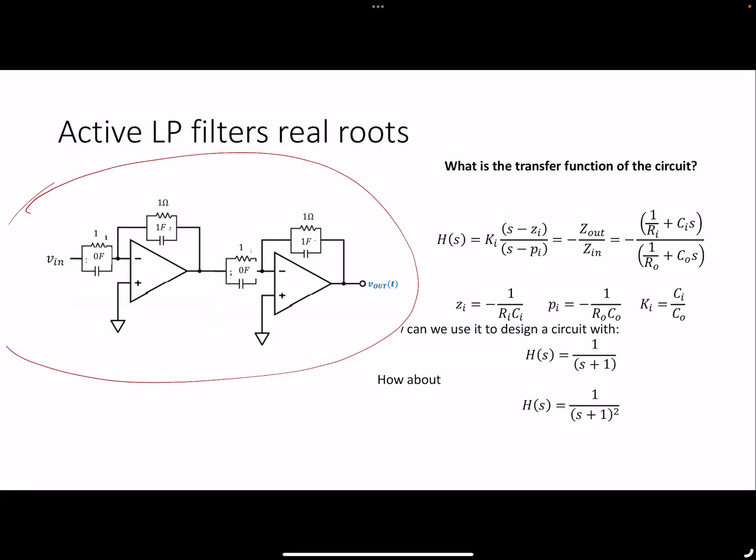In an exam, you're either going to be given a multi-stage circuit and you're going to have to figure out the poles or zeros, or you should be able to, if I give you an expression like K (s+3)(s+5)(s+7), design a filter that satisfies that. If you can do that, that's it. That's all you need to know.